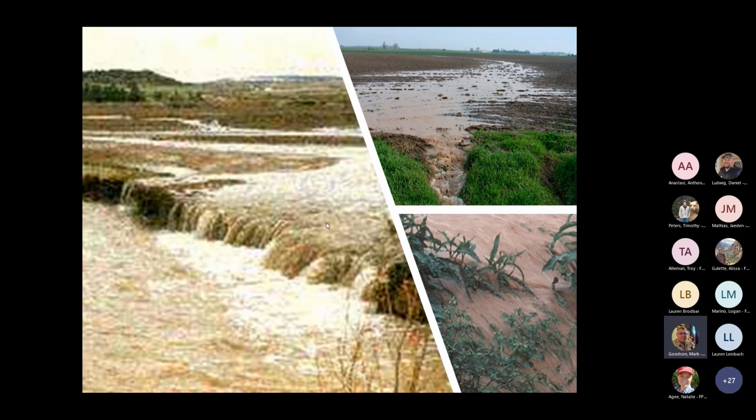Okay, it's important to notice that the problem isn't at this location. The problem is upstream. In the upper right-hand corner, we can see there's no permanent vegetation. There's no long-term vegetation. There are no plants. Actually, we should just talk about it. Long-term plants fix the soils. Plants improve the soil health. Plants help to maintain the dynamic properties that we want to achieve in the soil. So because there are no plants, we're having this sediment load working its way with the runoff.